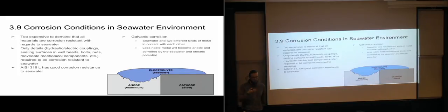So one way around this would be to add a third metal in here. So if we had strapped on a zinc anode here as well, the aluminium might be saved, but the zinc and aluminium are fairly close to each other, so it might not be saved by it, but it should be a little bit safer at least.